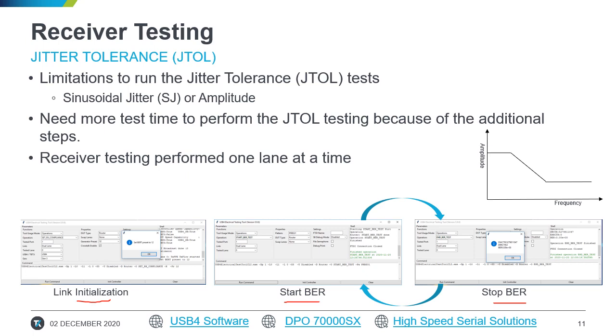So this will be a multi-step process, and for each step size increase, we need to see whether errors occur or not. If errors occur, you can reduce or increase the step and go to the next level. And once we fine tune and find the boundaries, then you can run for a longer duration for BER12 or BER9 duration.